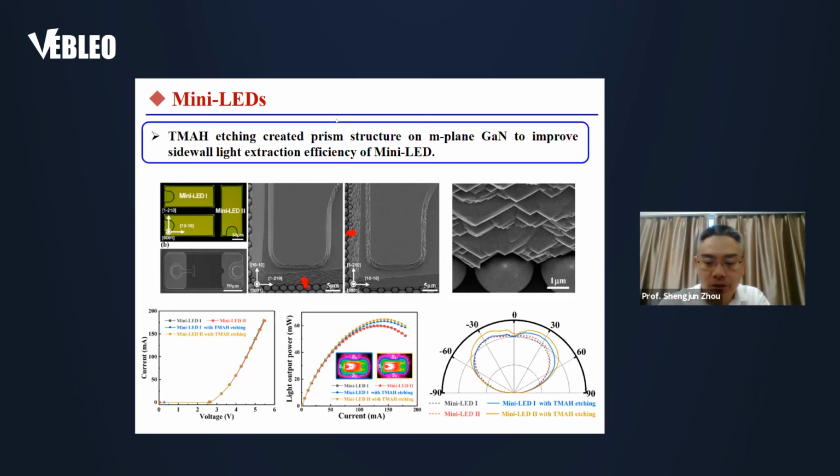Internal quantum efficiency of UV LED is limited by high density of threading dislocation. We compared the effect of different nucleation layers on performance of UV LED. Without nucleation layer, gallium nitride does not coalesce to form big gallium nitride grains.